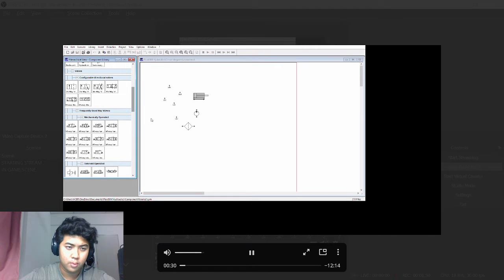And then we will pick a two-way valve with manual and spring return, and the function is for pneumatic applications where the supply of air must periodically be closed off. After that, we will pick a three-way valve with push button and spring return, and the function is to control a single acting cylinder, driving pneumatic actuators, blow off, pressure release, and vacuum applications.